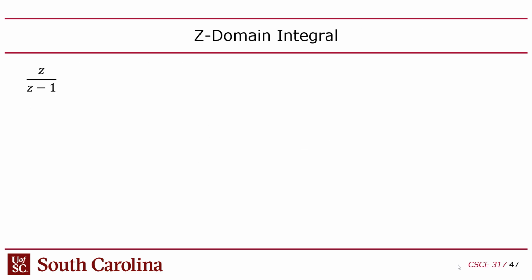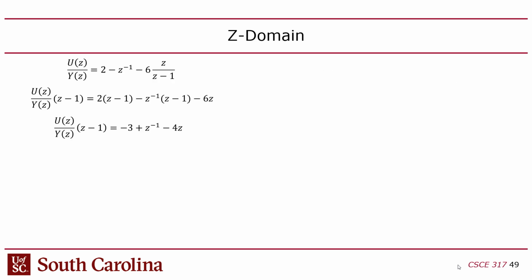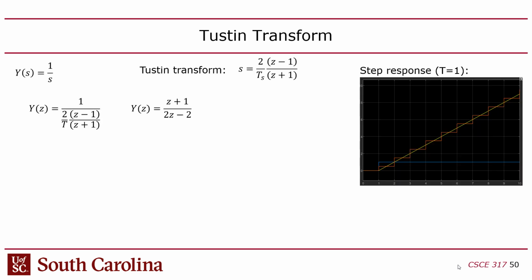Okay, so my point is that a part of the Tustin transform is, you basically plug this in for S and you get a Z domain, right? But there's a little detail in here. There's this time step in here, the T sub S. And that is your time step or the sample period, right?